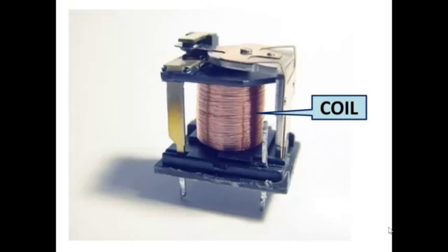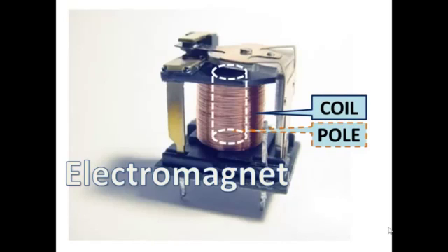The most dominant feature of a contact relay is the coil. The coil is also the load in the switching circuit. So the contact closure being relayed is controlling the coil, which controls the contact of the relay. The coil is wound around a pole piece, a rod of ferromagnetic material.